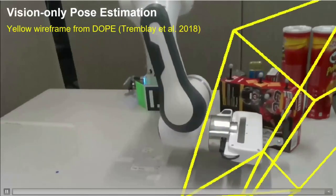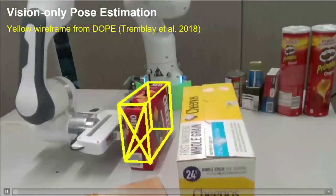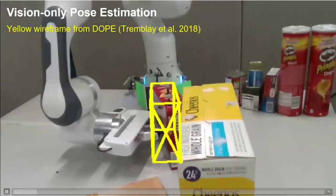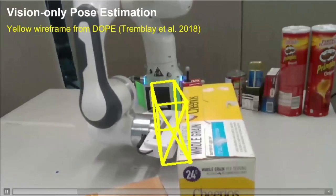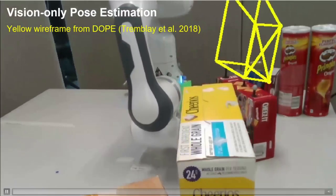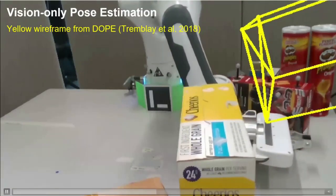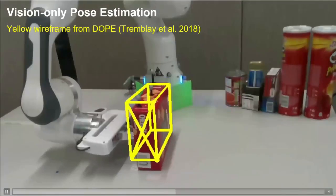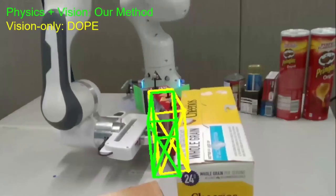So we have encoder information from our robot. So what it means is that if we have an initial good estimate of where the object is, and if we know where the robot is at the beginning, which we do, and if we know how the robot is moving, which we do, these are available information, then we can also predict how the object is moving based on physics, right? So maybe we don't only rely on vision, don't only do vision on the pose estimation, but we can do physics plus vision.